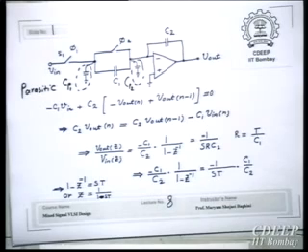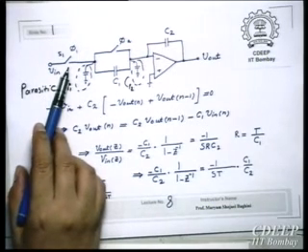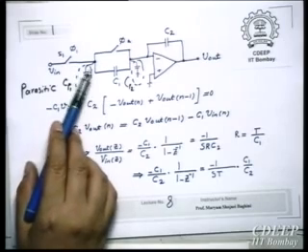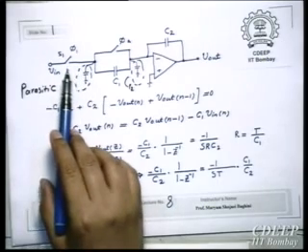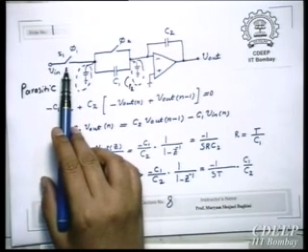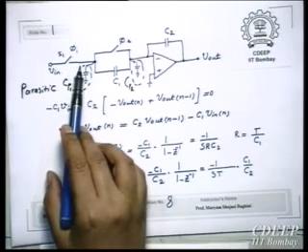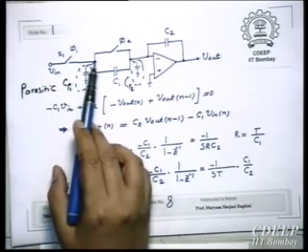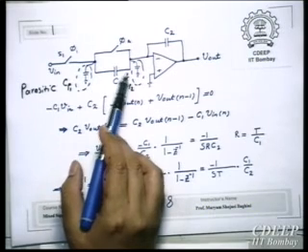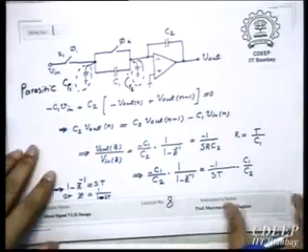Yeah, there is one point here. Because when you open the switch, there are two things. One is clock feedthrough, and one is discharge of the charge which was stored on the channel of phi 1. Right? So that will happen, and this will go through this and this as well. Therefore, this will create charge. Yeah.